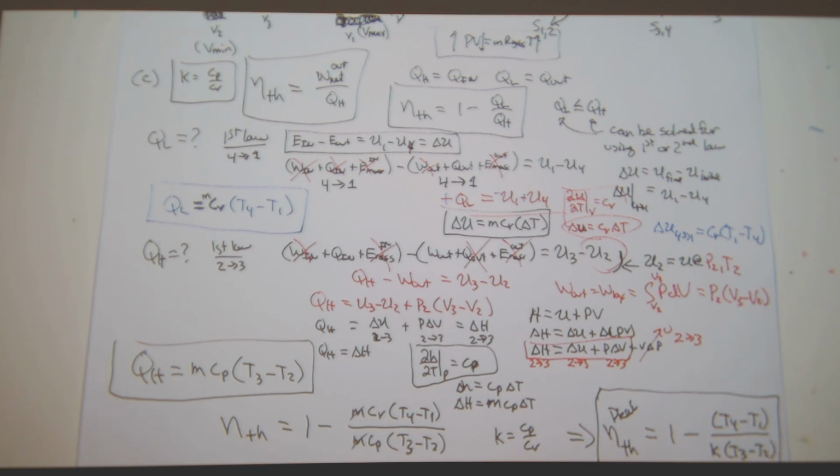Can we always assume that? Well, if the process doesn't talk about mass transfer, right? So for all these ideal gas cycles, assume no mass transfer. So it's constant mass. If there's no talk about mass transfer, it has to be constant mass. Think about what is the energy associated with mass. There's no mass in or out, so what happens to the mass of the system? It's just mass balance, right? Mass in equals 0, mass out equals 0, change of mass of the system equals 0.